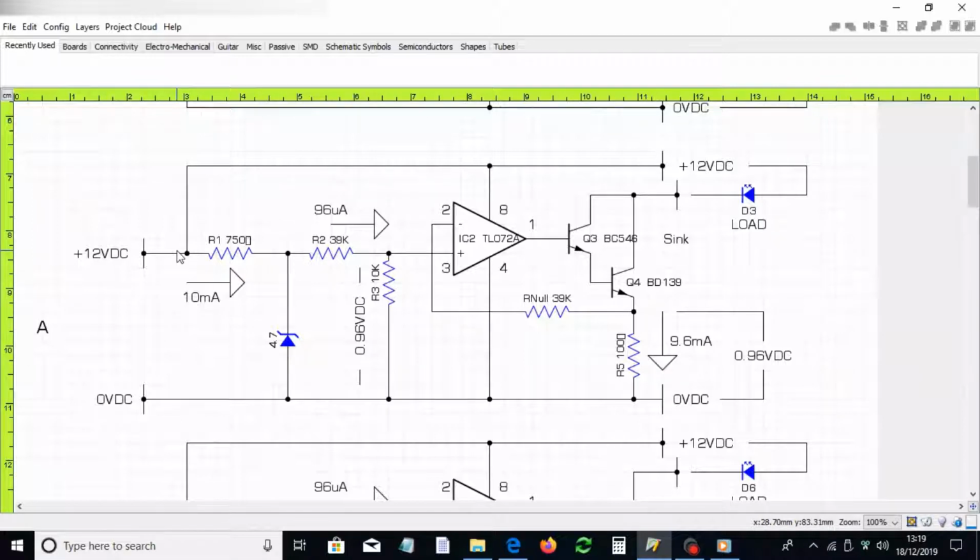As you increase and decrease the compliance voltage from, say, below 5 volts to maybe 30 volts, you change the current through R1, which affects the Zener diode, and the Zener diode voltage will change very slightly. You can compensate for this, and instruments of old, some of them used Zener diodes, and the way you can improve this is by selecting Zener diodes.